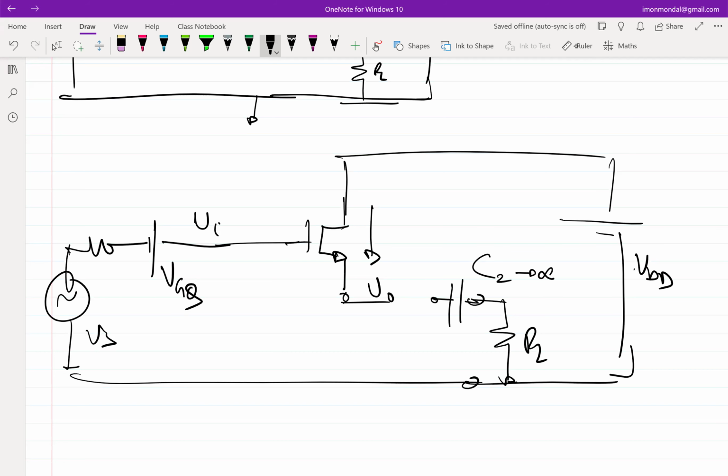So it's not as if you can pass the bias current through RL. Another problem is that RL itself can vary. If RL varies, then the quiescent current to the transistor might vary. So you don't want to connect RL directly to the source and use it to both set up the quiescent current and also act as the load. Ideally, we would like to decouple RL from the setting of the quiescent point.